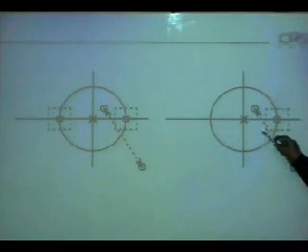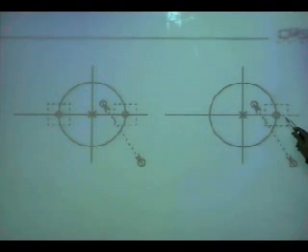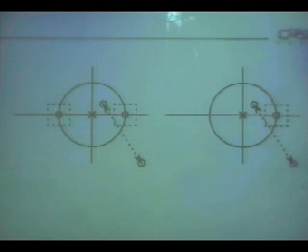This is anti-symmetric and m is odd. You cannot have a low pass filter, but you can have a high pass filter. That's what the tool did. Once I forced it to design for m is odd, it designed it, because you can have a high pass filter in this type 4.